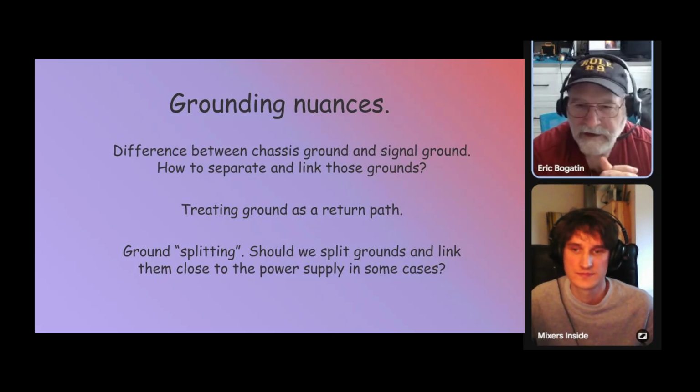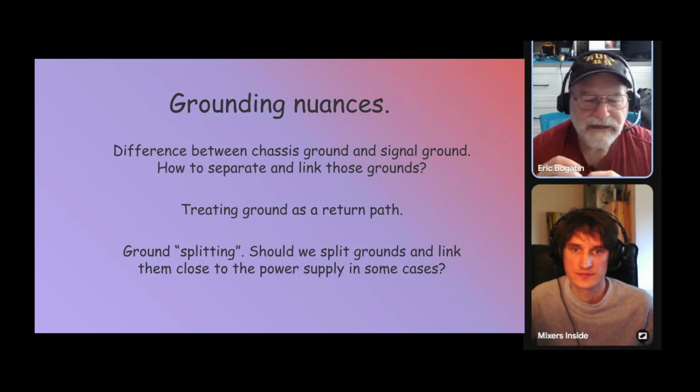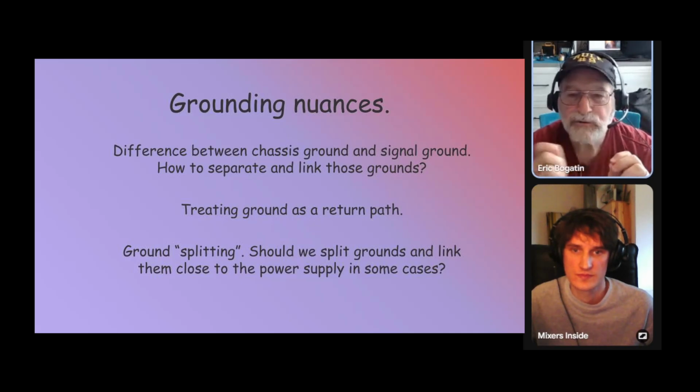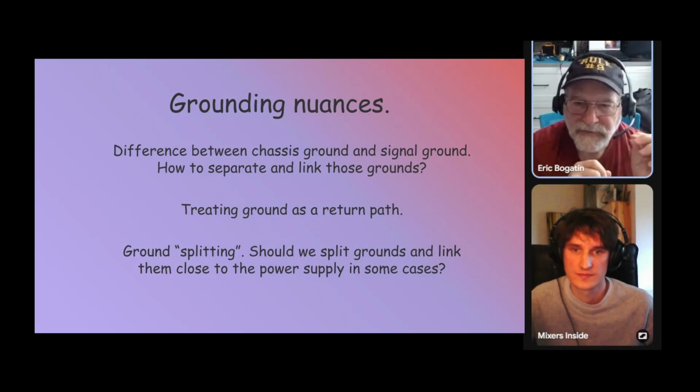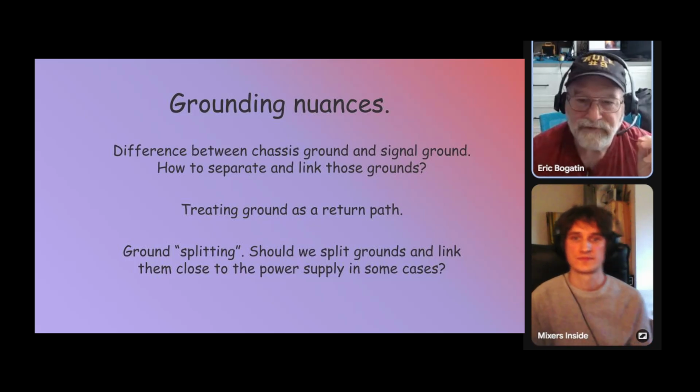Another way of reducing that noise is we use a separate conductor for the reference of the sensor. It's like treating it as a differential pair. Even though they're both connected to the ground node, so in the schematic you don't see a difference, you have to know when you do the layout, I'm going to have a separate trace that goes from the phono jack or the microphone input to the amplifier.